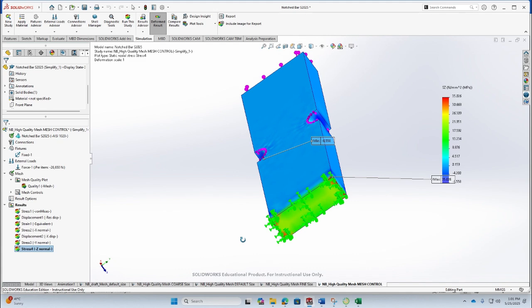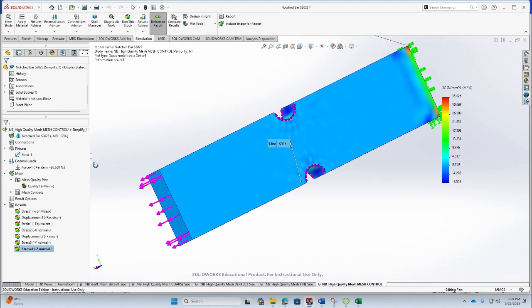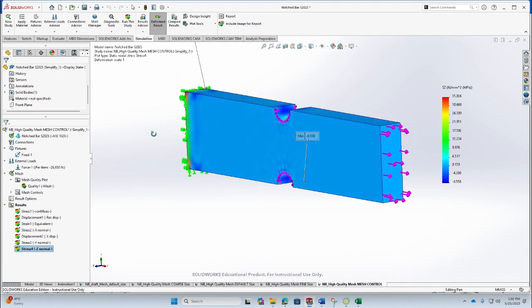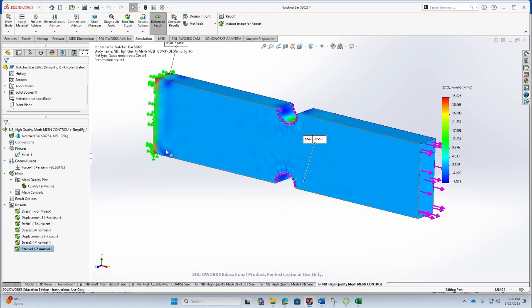where the supports are. Now in our case, these supports, because we did not model actual support, are not necessarily very realistic, so we will not be too much bothered about it. In reality, depending on how you have actually built in, then you may be able to see what the effect of support is. Right now we have completely made it fixed. So if you were to completely fix it, like by putting it inside, let's say, something, and then welding it all around, then this is the kind of stress that you will get.